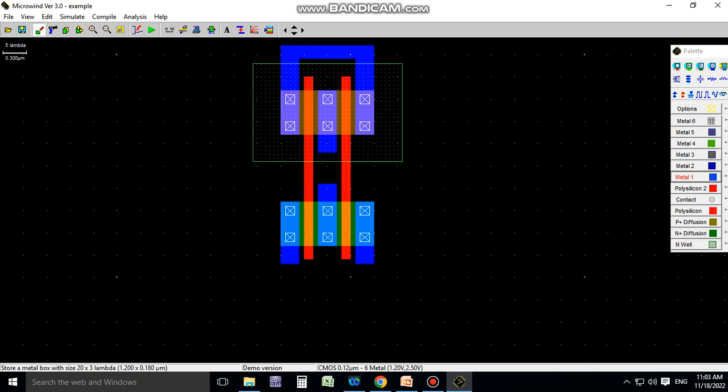This one is the drain and this is the gate, and here we take drain, gate and source. So this is the drain and source connection, and this one is the series connection. This is the source terminal of our first MOS, so we connect it to ground. Now we supply the VDD. The sources of both PMOS are connected to VDD. In order to avoid floating, we also connect VDD to the N-well. Now the output is taken across the drain terminals.